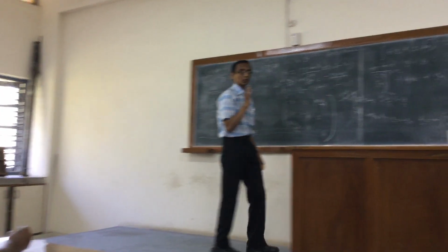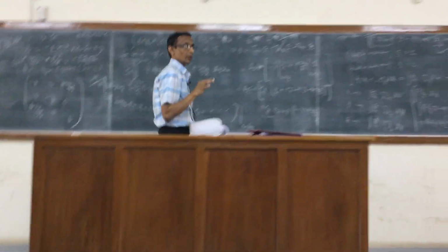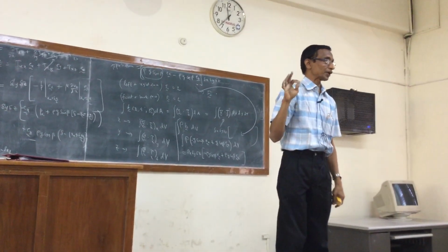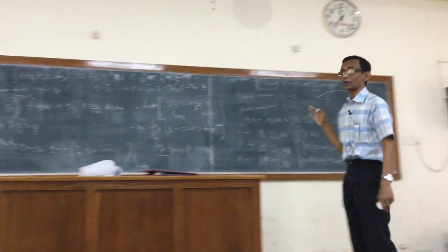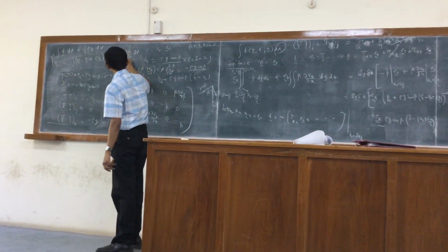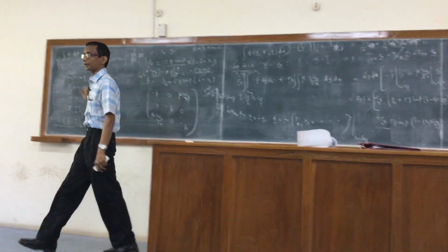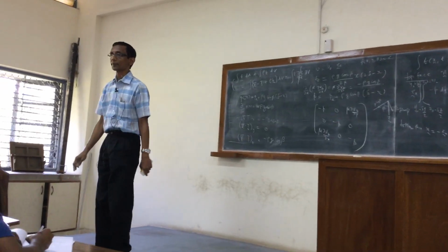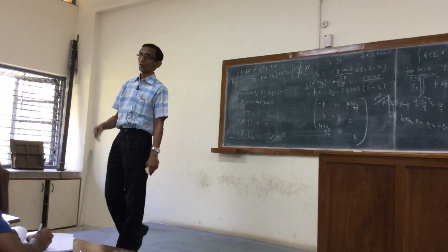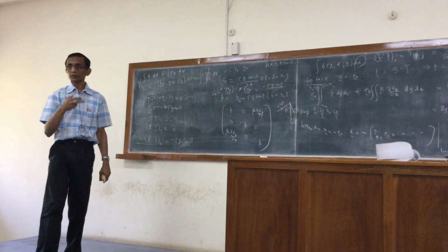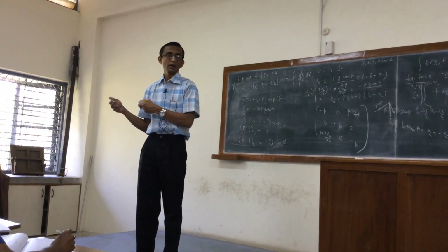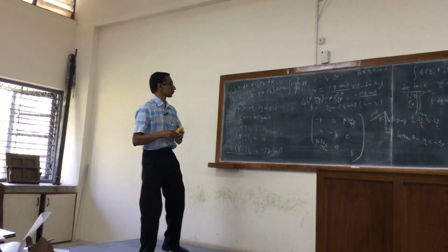We've just seen that for the one-dimensional flow, a steady one-dimensional flow, the inertial terms vanish identically, right? So dv by dt, which you may call capital D v by D t, is identically zero in this case. So if I wanted the total force on the whole body element, I need not even have calculated the individual contact and body force.